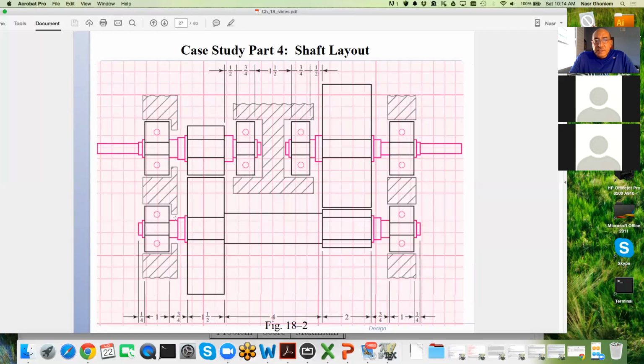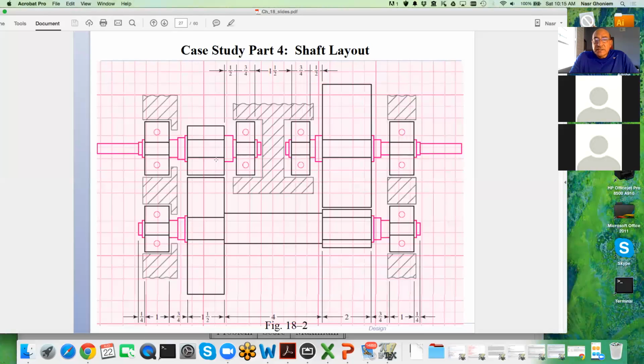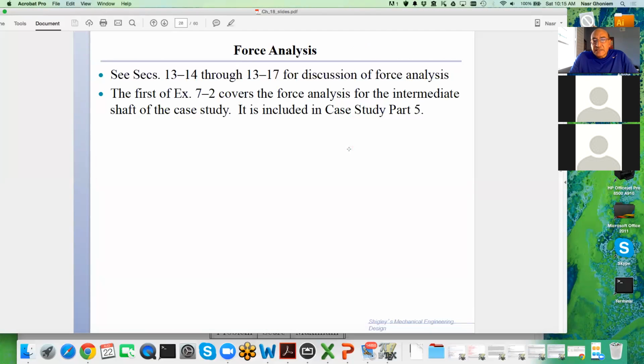Okay, so this is the selection of the gear. So the gearbox looks like this: there is an input shaft, and the output shaft is in line. So that's a design requirement. So the center line for input is the same as the output, and that also puts a constraint on the size: gear 2 plus gear 3 should be equal to gear 4 plus gear 5. I'm talking about diameters here. So that's a requirement that helps us in the sizing.